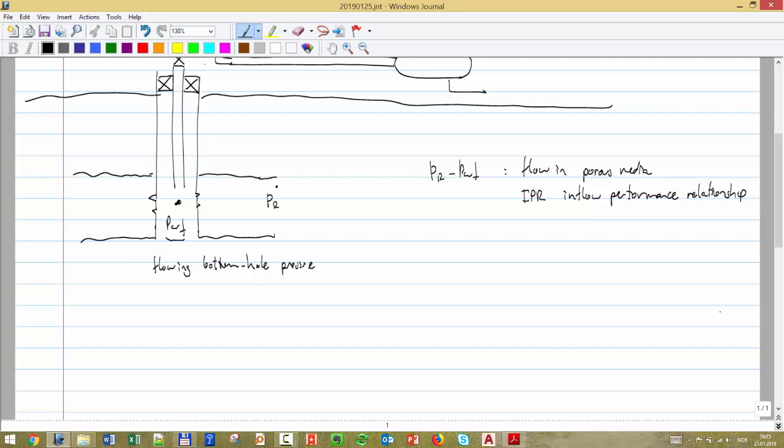If we take time out, then we get an equation for liquid, for undersaturated oil: J times PR minus PWF. And for gas it was what we call the backpressure equation: C times (PR squared minus PWF squared) to the power of n. Because we could take time out.